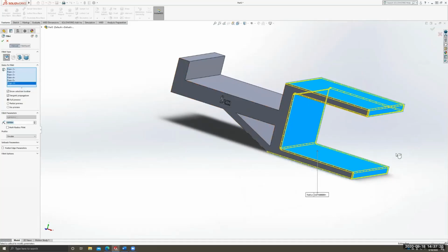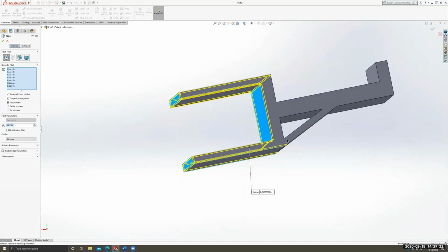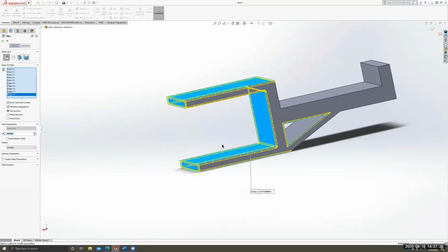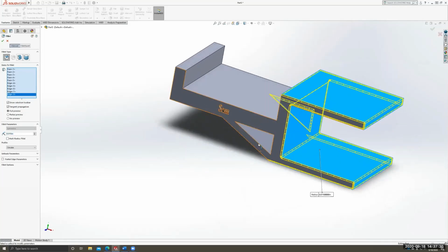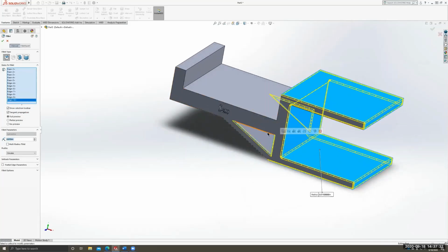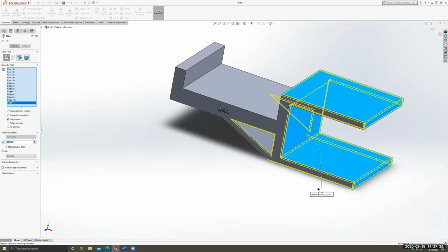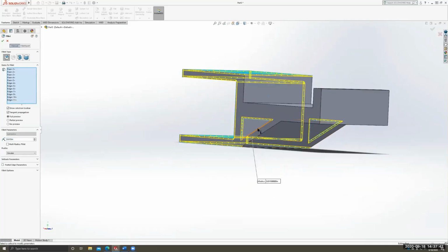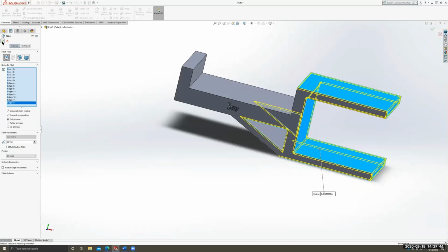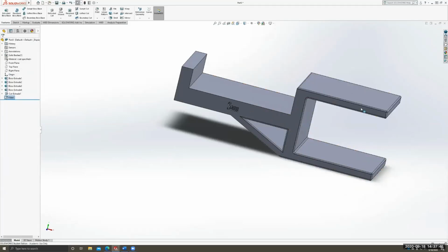I want to do this one, because when you 3D print things, sometimes it has sharp corners. And sometimes you might cut your finger, and that's a big ouch. So I'm just going to fillet those. Here is your list of things to fillet. Say you want to delete edge 8, just right click and hit delete. And then you can just go back and reselect. Okay, so those are my fillets.